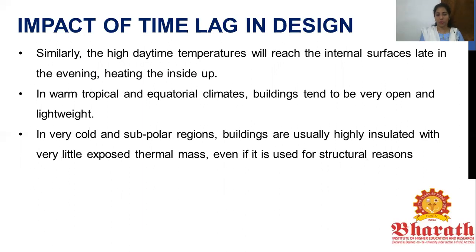Whereas in warm and tropical equatorial climates, the buildings tend to be very open and lightweight, so this lag is not needed. But then again, going back to very cold and subpolar regions, buildings are very thick and highly insulated. So they have very little exposed thermal mass, even if it is used for structural reasons.